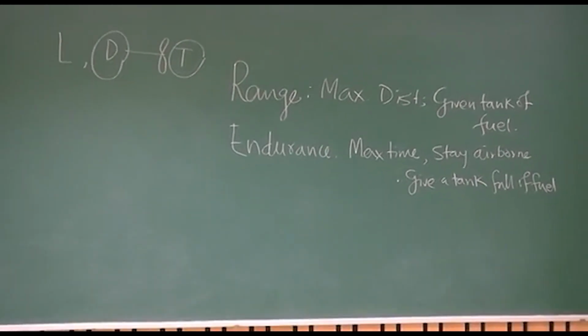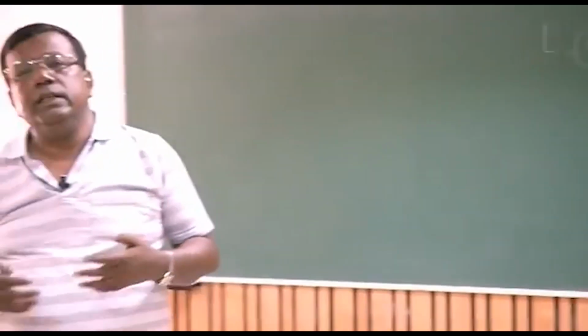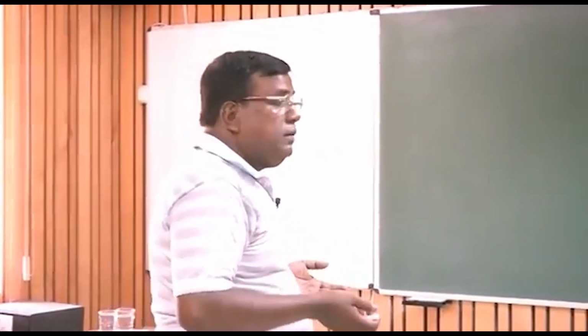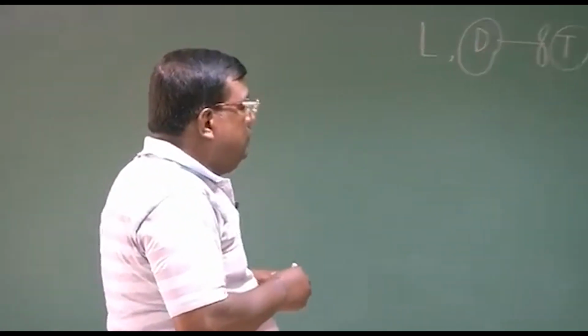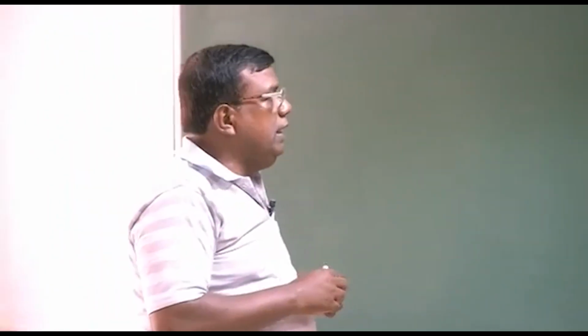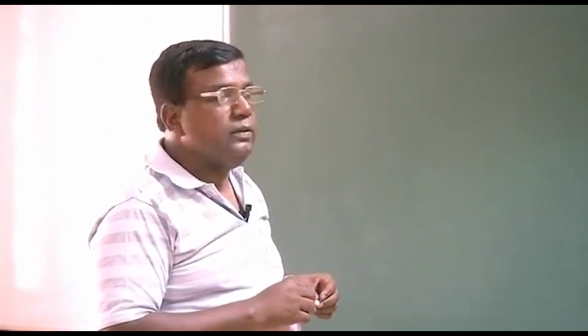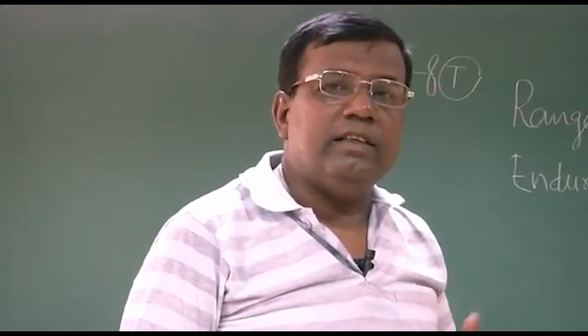The answer is not so straightforward, because as I add fuel, it adds to the weight, and weight changes the wing loading; it makes a cost. So for a good designer, one needs to optimize the aerodynamic characteristics so that for a given tank of fuel, I can get maximum range or maximum endurance.